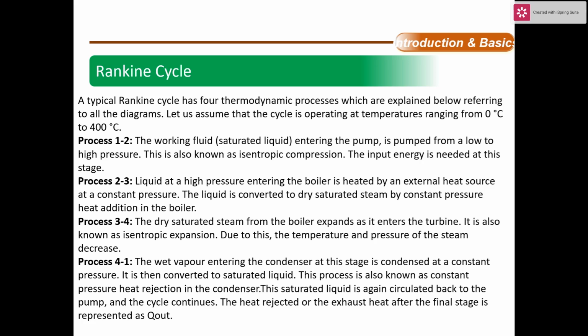The working fluid entering the pump is pumped from low to high pressure. This is also isentropic compression. The input energy is needed in this process.